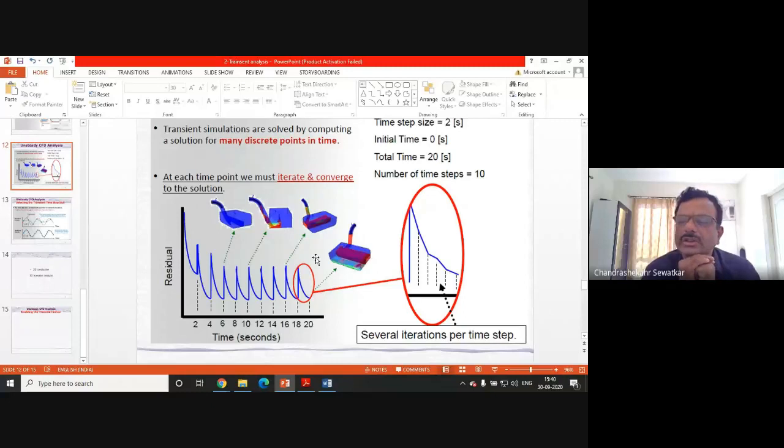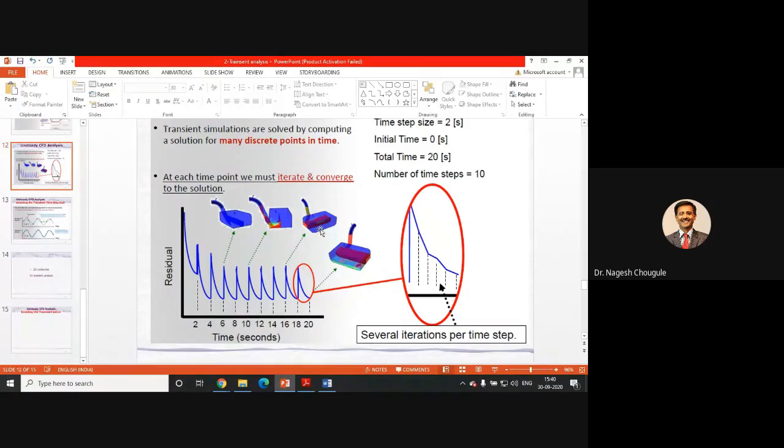There is another question. Does ANSYS provide the location of a specific temperature, for example, 250 degrees? Yes, definitely. You can locate a particular point with the help of datum points, and at that point you can find out the temperature or any property. You can even define your own variables, as I explained yesterday. For example, if I want to know the Nusselt number, with the help of the heat transfer coefficient I can define my own relation and monitor it at any location. But for that, initially you have to define some geometries, like a datum point or line or any other surface patches.